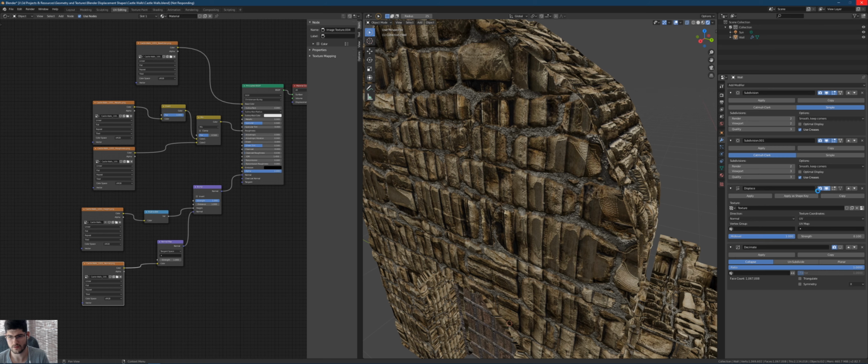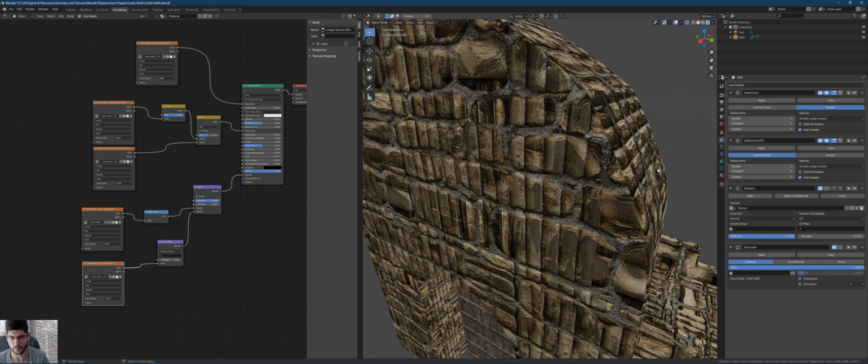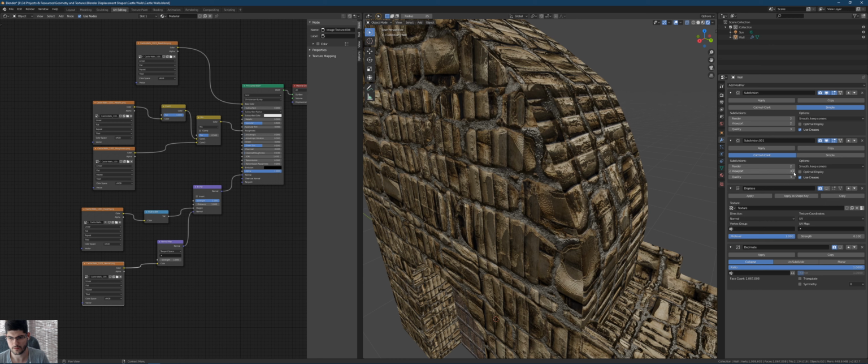So I've just taken out these two modifiers. I've deactivated them in the view, in our options, and then I am going to increase our viewport resolution. We were at 1 million faces, and I want to go to 3 million. So let's just see what we get over here once this calculates. As you can see here, 1 million. Come on, work it out. Need to get a better computer, it seems. It's just not going fast enough. Blender is taking way too many resources, way too much time to finish off the process. So we're now at 4.2 million.